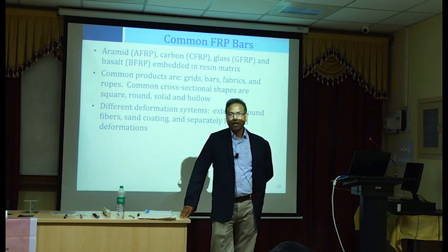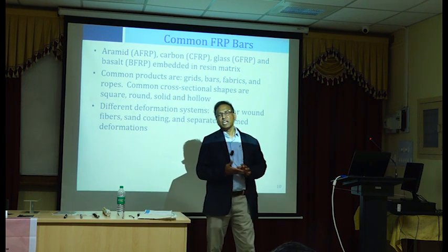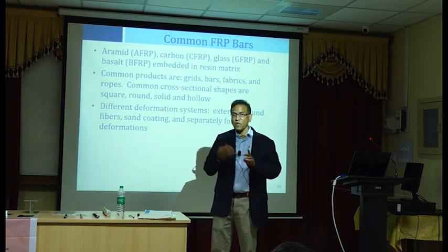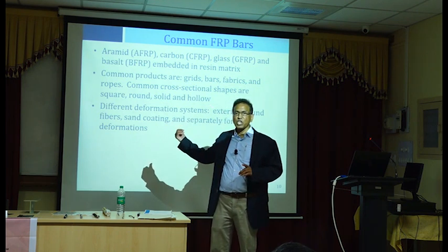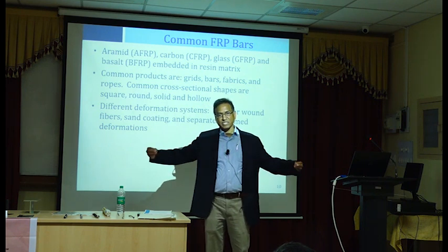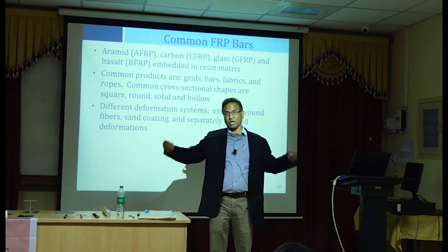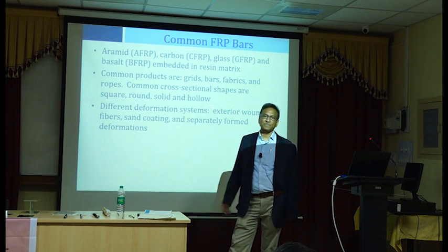Generally in pre-stressed concrete, you worry about creep in concrete and relaxation in steel. Those are the two things you consider. Whereas in FRP reinforced concrete beams, you consider creep rupture in FRP bars. We are not looking at creep of the concrete, we are looking at the creep rupture of the bars, so it normally governs the design.